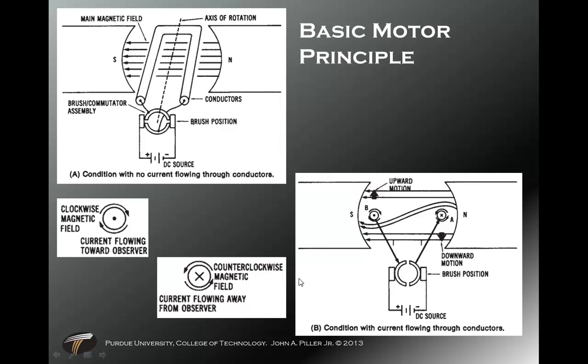A little point of schematic design: a dot in the center of a conductor means that current is coming towards you. An X in the center of a drawn conductor means current is going away from you. Imagine current as an arrow. That's the point coming at you. That's the feathers leaving you. Okay? So here, B has current coming at us. A has current flowing away from us.